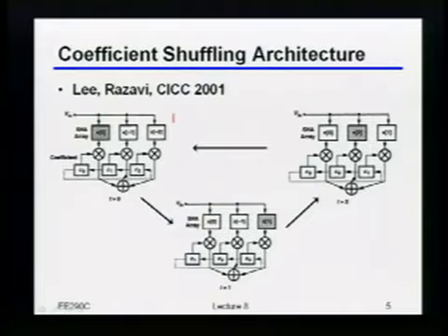Let's say that I wanted to build this particular filter where, as an example, C0 is the main tap, C1 is the first post cursor, and C2 is the second post cursor, right? So the basic idea would be that I could sample these inputs in these three samplers here. Then in the first phase, feed them to these three multipliers, okay? So on that first clock phase, I've gotten that filter that I wanted, right?